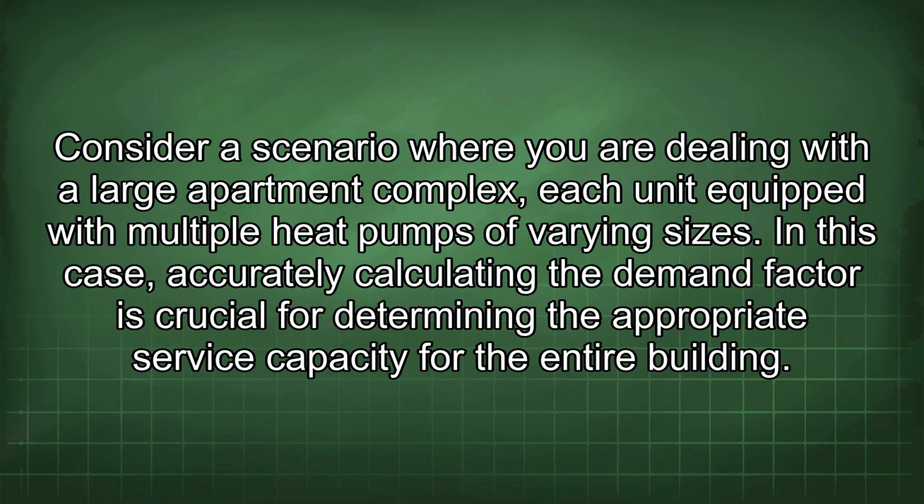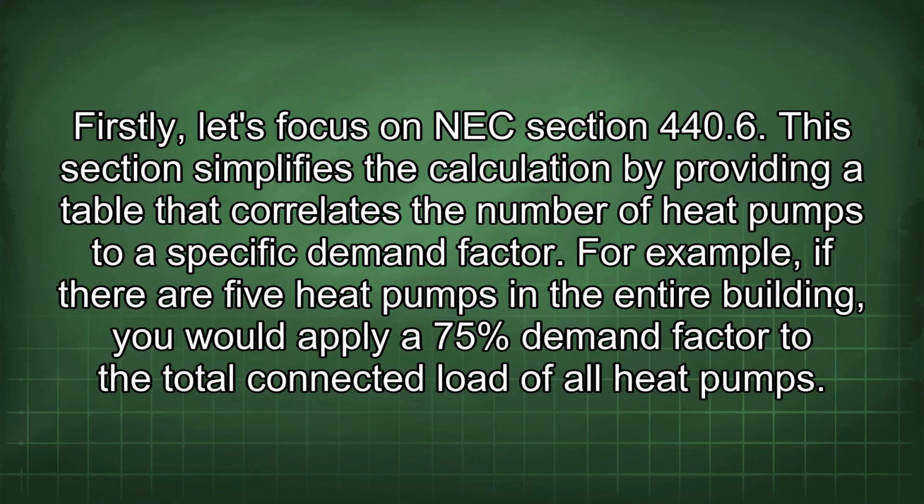for the entire building. Firstly, let's focus on NEC section 440.6. This section simplifies the calculation by providing a table that correlates the number of heat pumps to a specific demand factor. For example, if there are 5 heat pumps in the entire building, you would apply a 75% demand factor to the total connected load of all heat pumps.